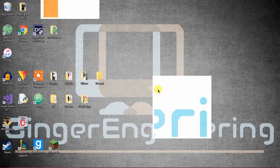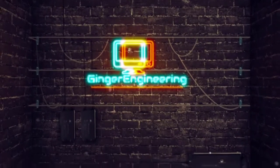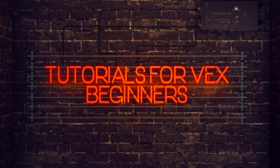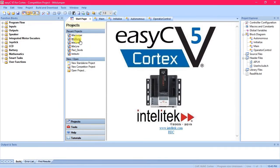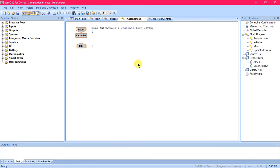In this video, I'll be showing you how to program and use a jumper pin using EasyC V4 or V5. Like always, we're going to open up our program, open up our project that contains our robot's code. Then we're going to head over to Autonomous.